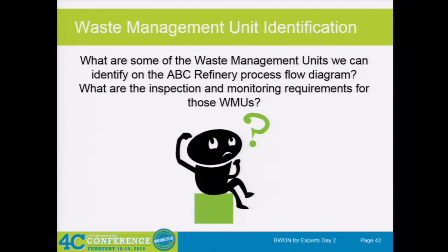Some sumps are actually kind of tanks that are inside, say, a box. And if it's vented to a closed vent system, you would need to ensure that you're capturing the lid in the closed vent system, like Mary Claire was saying, which would be the no detectable emissions. So if you're looking at it as part of an IDS, then it's just quarterly visual.